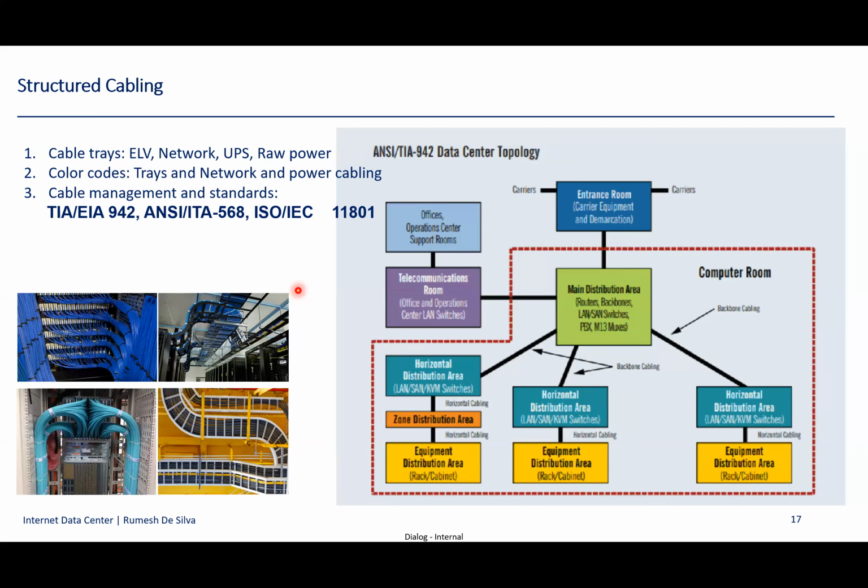And also, once you are putting a label, please put near end and far end both. Don't put far end only. Please put near end also, because that will be really important while you are troubleshooting, right? So I have discussed the basic things related to structured cabling. Definitely, once you are working with a contractor or labor, you may get even a minimum 25 years warranty for that.